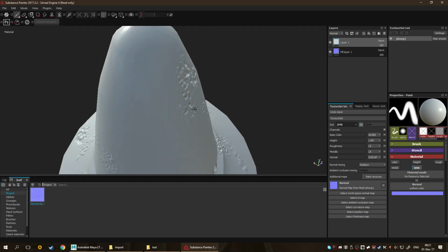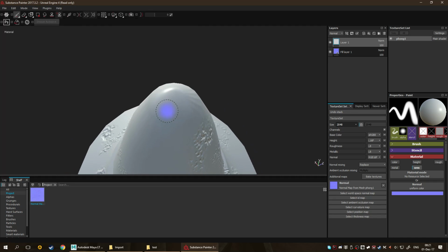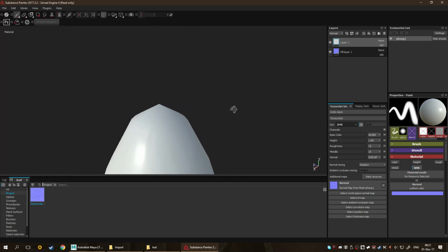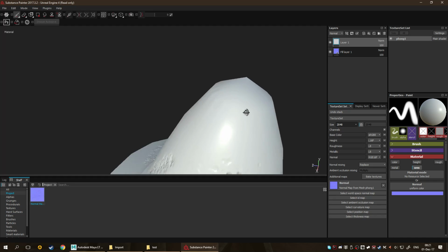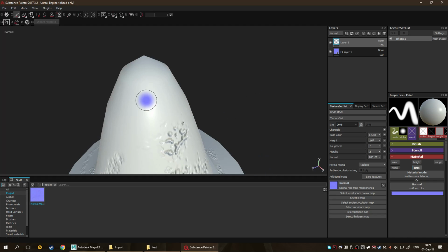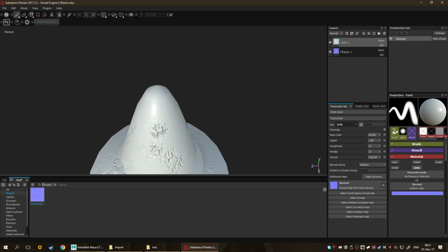Now, obviously, I'm kind of messing up the light calculation as well, but it's a sacrifice you're going to have to make, unless, of course, you want to go ahead and do this the manual way. Obviously, you wouldn't want to be doing this to fix your model if it is possible for you to do so topologically. But post-mortem, if you've already done all the texturing, and you suddenly see a small problem in your normal map, you're like, oh, I gotta fix that. Well, this is a way to fix it, all right?